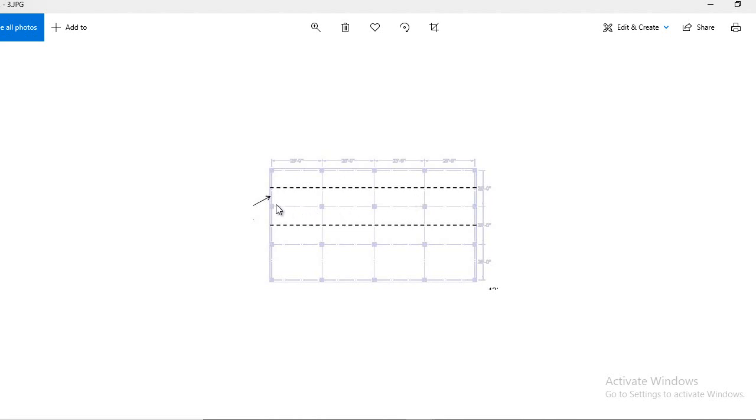And there will be, you can say, zero or a very small amount of unbalanced moment due to the difference in geometry. Because let's say if this is 25 feet and this is not 25 feet, let's say this is 15 feet, this is 18 feet. So due to the difference in geometry, there will be some kind of unbalanced moment.